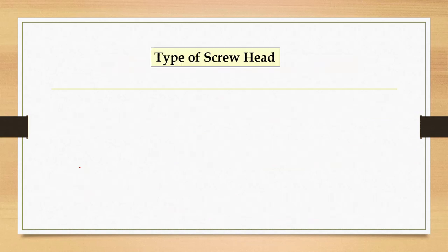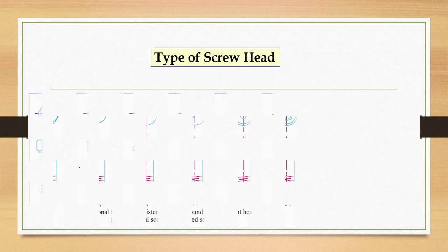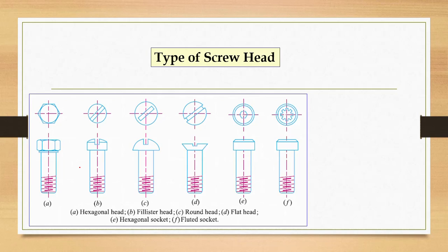Okay, so how many heads does a screw have? Now when you talk about screw and head, most people are confused between the bolt and the screw. As I mentioned in the first slide, a bolt generally contains a nut, whereas screws are generally used where there is no nut. Actually, you do not put a nut, the threading is internal. Either you provide the pre-threading, or in case of wooden assembly, the thread will be made by the screw itself.